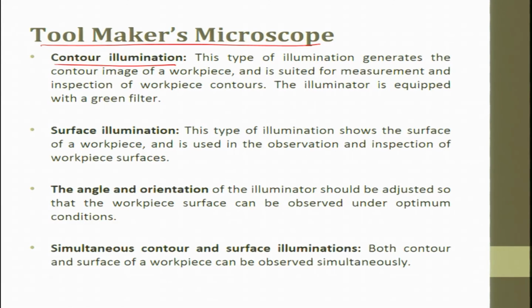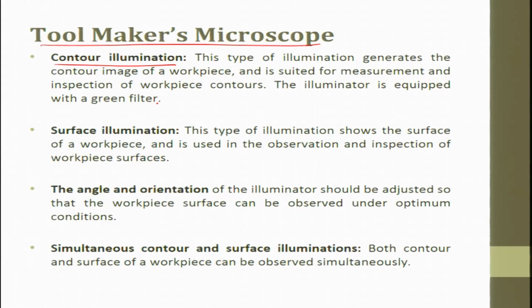If you can play with these parameters, then you can try to get more clarity in the image whatever you have used for measurement. Suppose if there is a workpiece which is too complex in nature, so what we do is we try to make a contour of it, put it in the eyepiece, or have a projector and then have it as a mask there, and then project the workpiece dimension on the screen. So, you can easily do comparison and try to also measure the deviations.